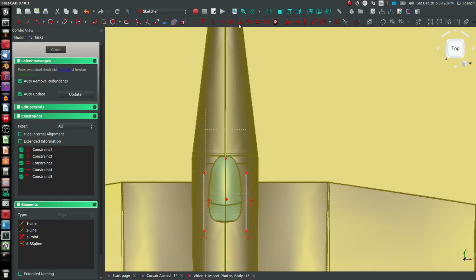And add in a sketch point that's coincident there and do a symmetric relation. There's our symmetric relation. So now our lines are going to be symmetrical, but we need to add a vertical. Control Z, Control Z. We need to make sure that this is vertical to that. There we go.